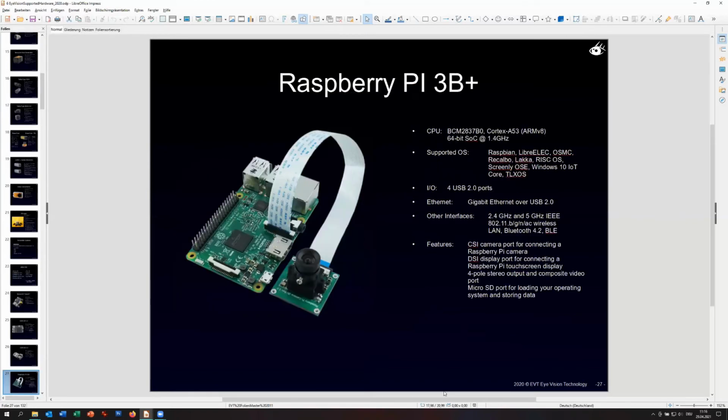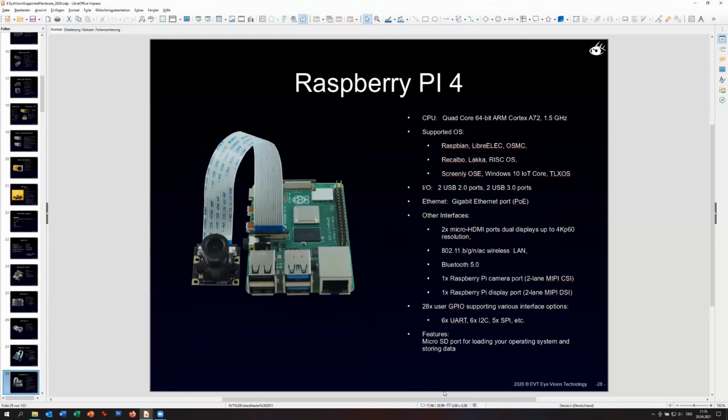Here you see, I think one of the most popular hardware units in this area, the Raspberry Pi 4, or 3 or whatever. Most of the others also have this MIPI interface because these CPUs have the interface, and the manufacturers added it. So you can simply use one of the MIPI cameras, connect it to the board, and capture images.